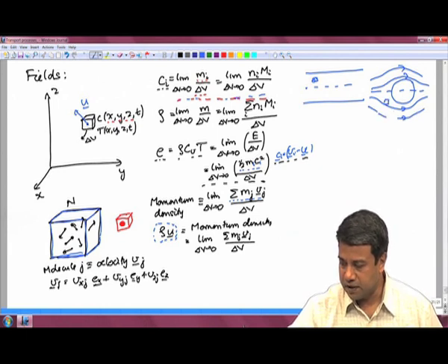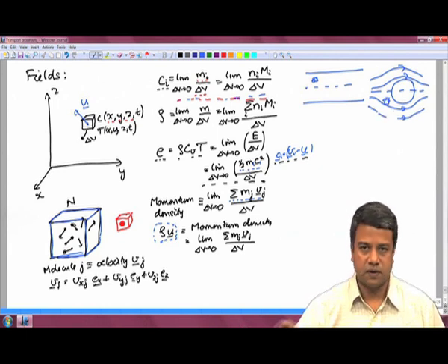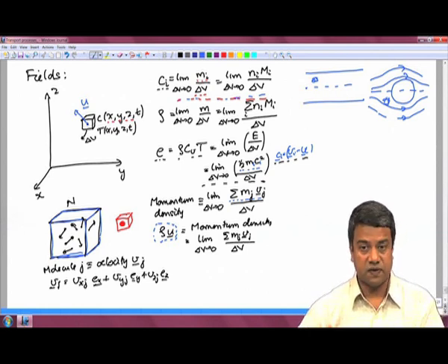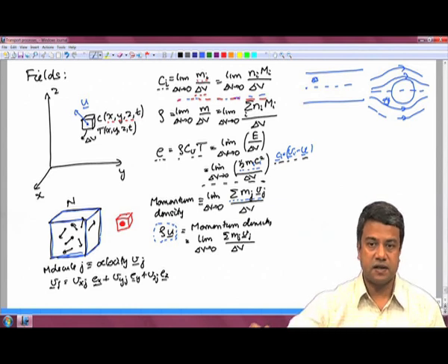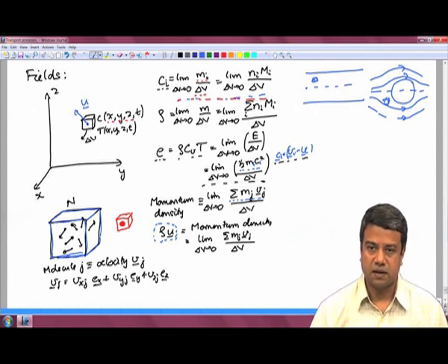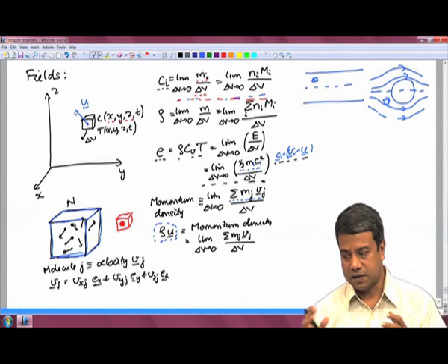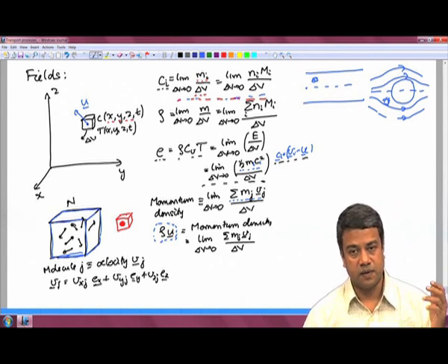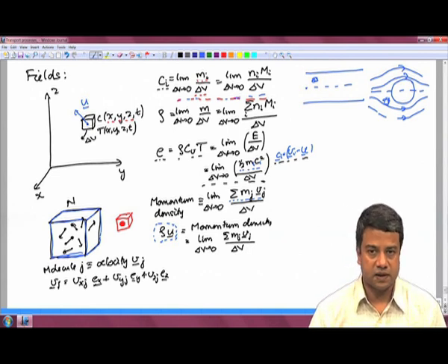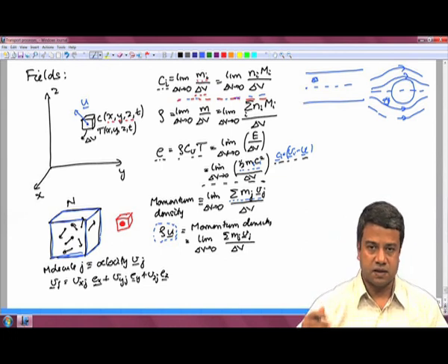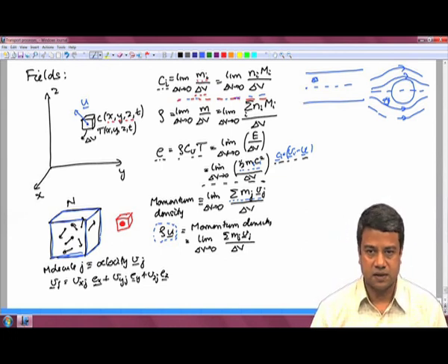the volume that I define has to be much smaller than the volume around the particle. If I define a volume that is large, then that will average over variations in the concentration in the vicinity of this particle or within the cross section of this pipe. Therefore, you need to have an intermediate scale, intermediate between the system length scale, the pipe diameter, the particle radius or the radius of the impeller in the case of the stirring in a tank and so on. You need to have an intermediate size which is intermediate between that large system size and the molecular scales.